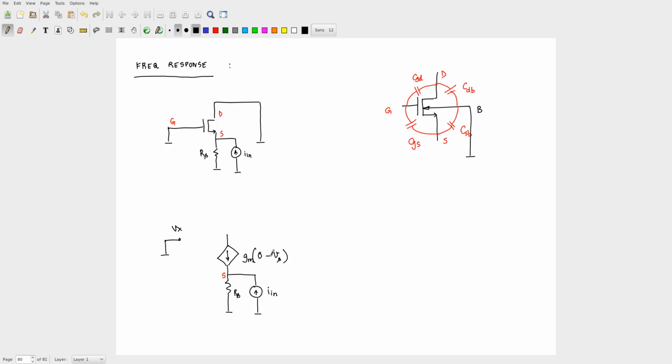Right? That is 0 minus Vs. And then what else do you have? That is connected to ground. Okay, now populate these capacitors here. This is not Vx, sorry. This is 0. Okay. Now, this was actually Vg, right? And that became 0. Okay, populate the capacitors. Where do the capacitors go? So just name the terminal so that everything is all right. So I have this to be my drain, right? That is source and that is gate. So first one is CGD.